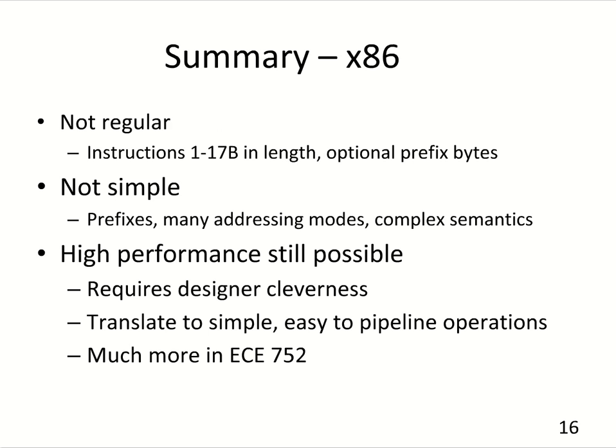Summarizing this lecture, x86 as an instruction set is definitely not regular. The instructions vary in length. There are prefix and postfix bytes and many other complications. It's not simple. There are many addressing modes that are supported, many instructions with their complex semantics. However, high performance is still possible, requires a great deal of designer cleverness, and the fundamental approach that's used these days is to translate the complex instructions to sequences of simple and easy to pipeline operations. If you're interested in this topic, we spend a lot more time talking about it in ECE 752.